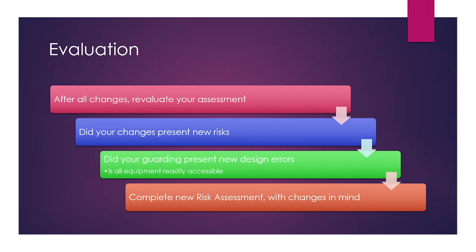So a common theme that I've seen in a lot of older plants is they put some type of a guard over any type of an electrical cabinet. So it makes maintenance technicians have to rip the guard off just in order to get into an electrical cabinet to change out a fuse or any of that type of instance. So does that present a new hazard or a new issue for us in the future? Or did you put guards over a valve manifold and you need to be able to access those valves in a readily accessible location? Yeah, it doesn't necessarily present an error or a hazard particular to say, but it does present an issue of not making it readily accessible.